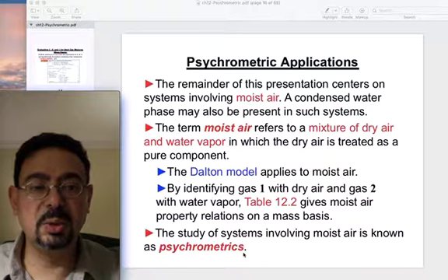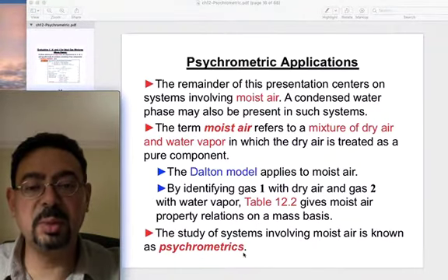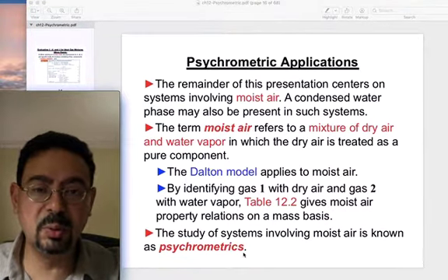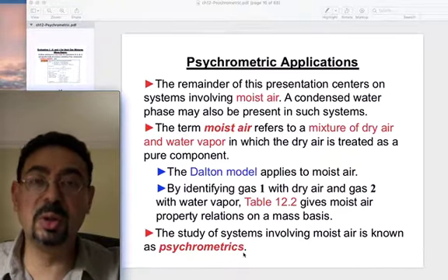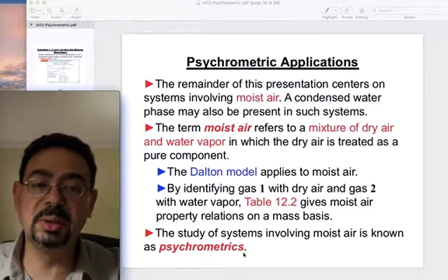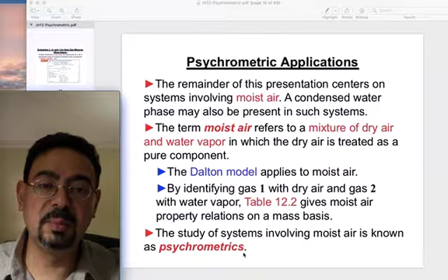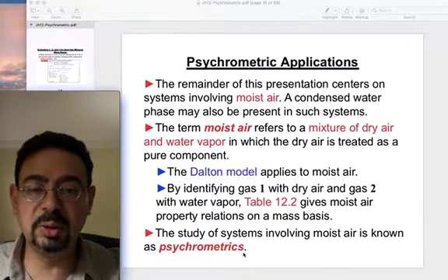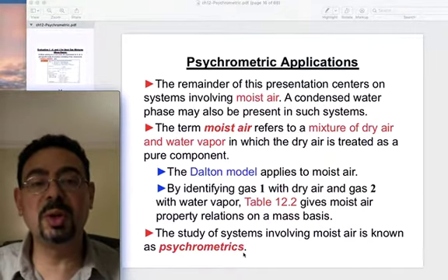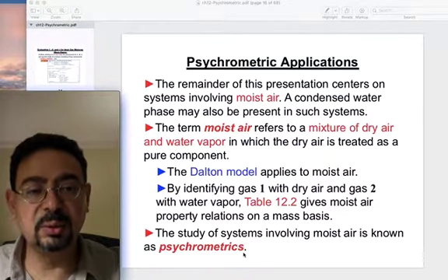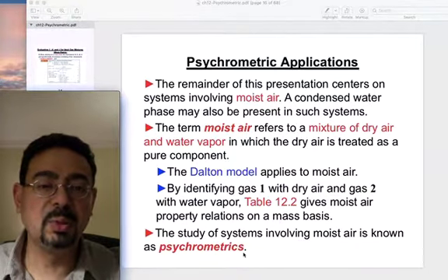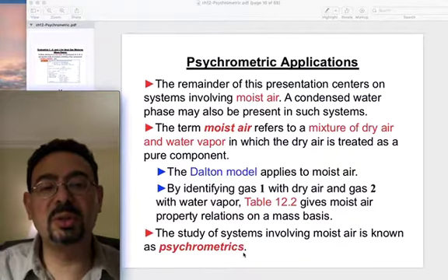And as you will know today, it's very important for HVAC application, for indoor air quality. If you want to make people feel happy in their workplace or their homes, you need to adjust not only the temperature. It's not all about just cooling and heating the air, but also the water content. The water vapor content is very important to make them happy, right? If it's too dry or too humid, people will not really be happy, as well as a lot of industrial processes that require not only temperature control but also humidity control, because it controls a lot of things like evaporation and drying, as well as in libraries and museums. So moisture content is very important, right?